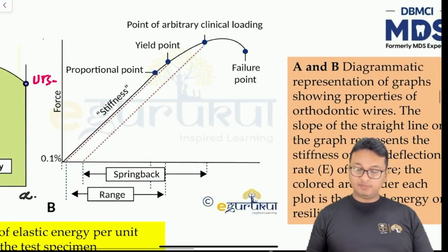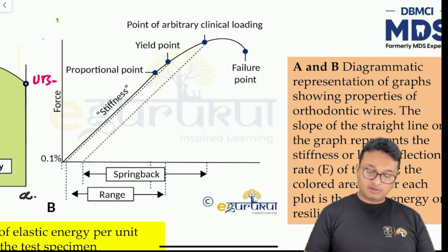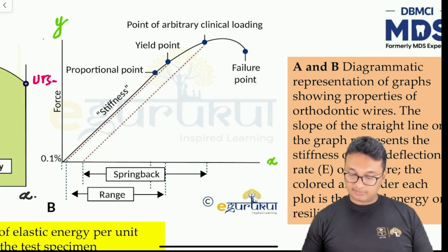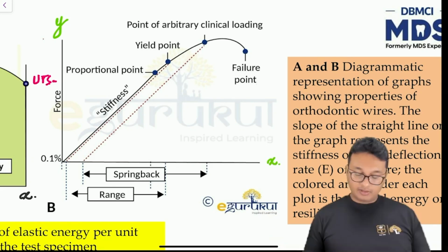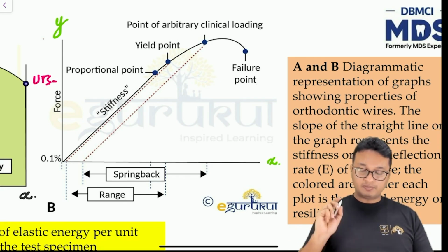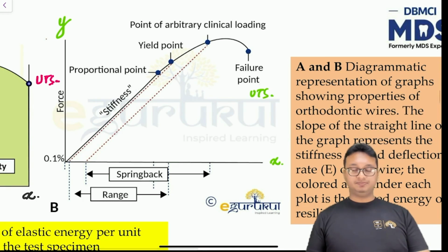Now, if you look at this particular stress strain curve, if you plot force on the y-axis and the amount of elastic deformation on the x-axis, or the amount of strain on the x-axis, you can see the proportional limit we have talked about, yield point we have talked about, failure point we have talked about. This is called ultimate tensile strength also.